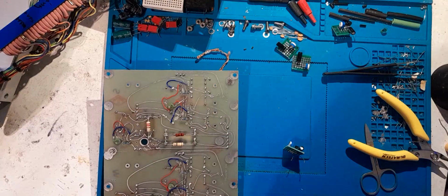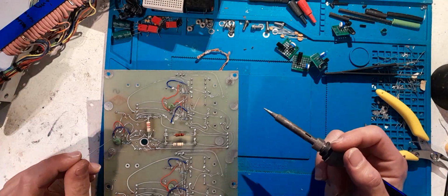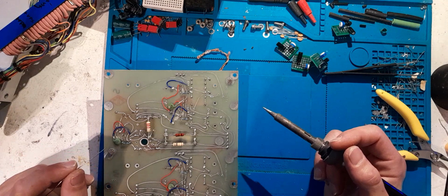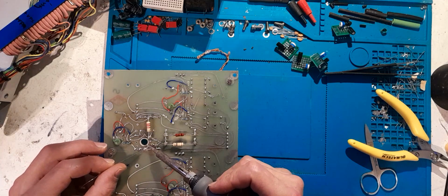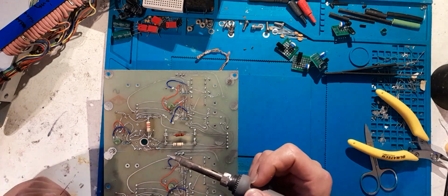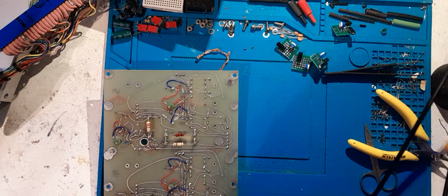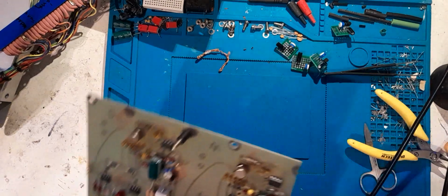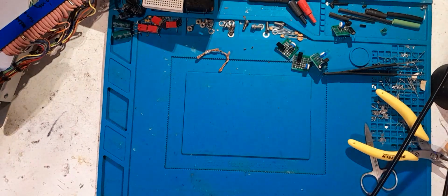If anyone noticed, don't worry. I just found out the hard way. Just went through a very long, why on earth can I only set the voltage on one of these, not the other, when they both wired up correct and I know they both work. Apparently I didn't solder one of the connections. I've done that now. Just wanted to point that out so no one watches the video and starts worrying. Don't worry, I found it. I'll go set the voltage on this one now. That's set at 5.1 volts. I just got to set this one at 5.1 volts.